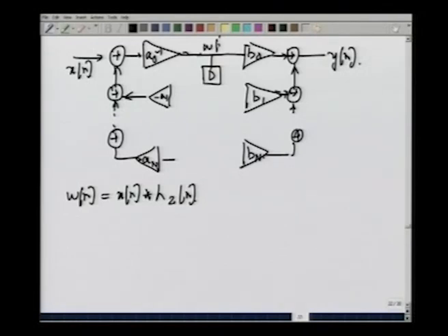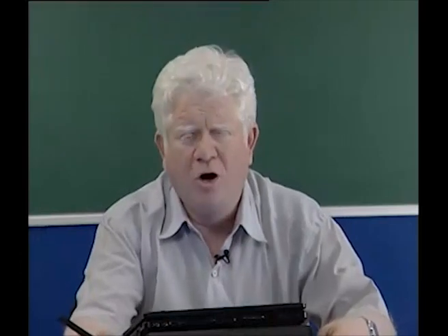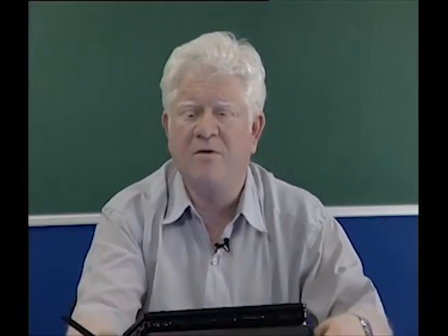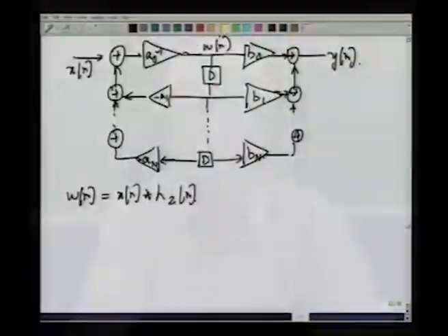This is wn actually, and this goes to both sides, so on until you finally have again a delay. One input going over here and of course the other input going over here. This is a further simplification of making block diagrams for systems described by differential equations, the general systems that we had, autoregressive as well as moving average systems. So this is the general block diagram.